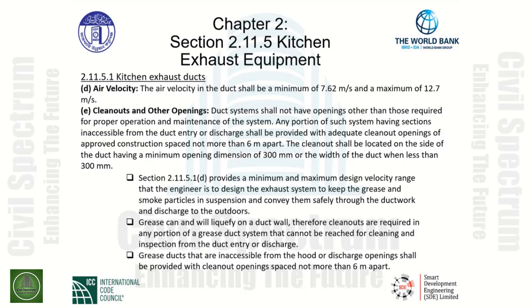Duct system shall not have openings other than those required for proper operation and maintenance of the system. Any portion of such system having sections inaccessible from the duct entry or discharge shall be provided with adequate cleanout openings of approved construction, spaced not more than 6 meters apart. The cleanout shall be located on the side of the duct having a minimum opening dimension of 300 millimeters or the width of the duct when less than 300 millimeters.